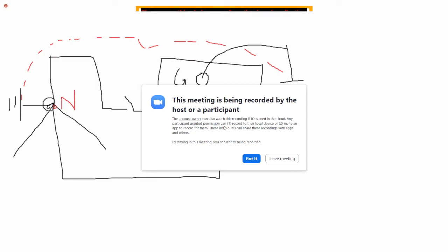Yes, sir. Okay, so please note down line voltage. You already wrote V line. It is a 440. It is phase and phase. It is red, yellow, blue in India generally. Phase 1, phase 2, phase 3 in some countries. RST in some countries. And L1, L2, L3. Line 1, line 2, line 3. So phase voltage is one phase and neutral wire.